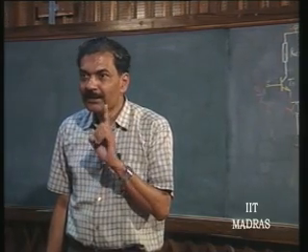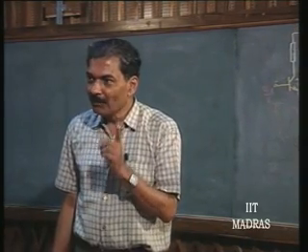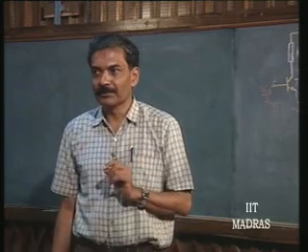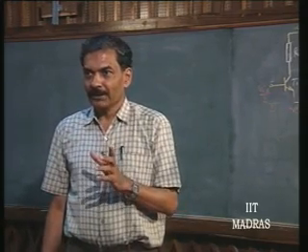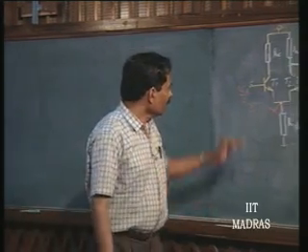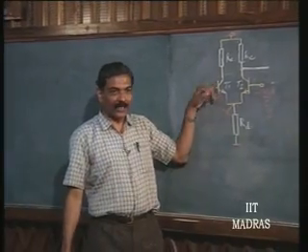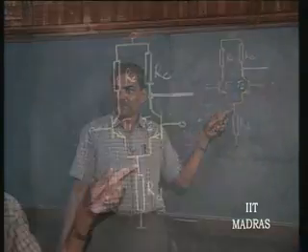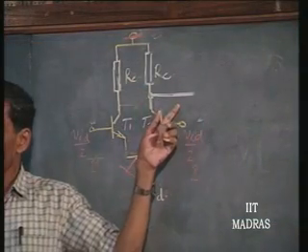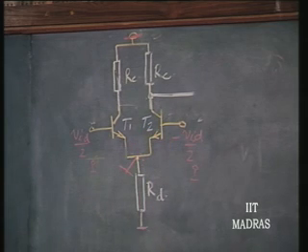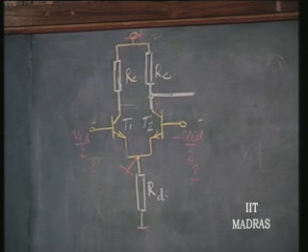Not if it is having common mode as well as differential mode coming. Is this point understood? Whatever increase in potential that arises out of the incremental current injected here will be removed by the current flowing in the opposite direction through the same impedance. So, essentially mutual cancellation occurs, and therefore, potential does not change. That means, in the incremental picture I can ground this.